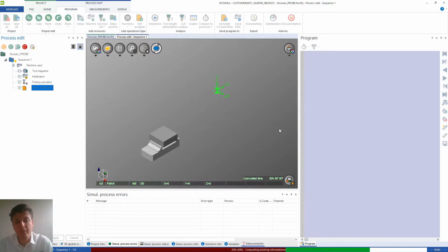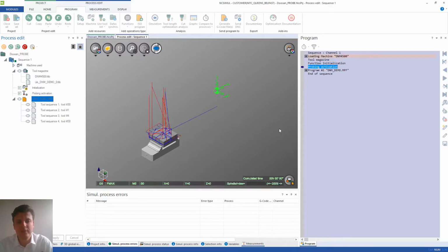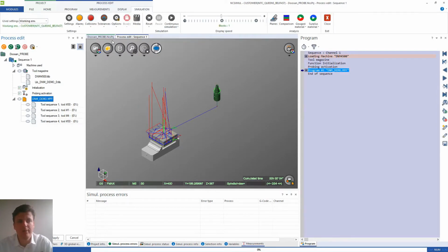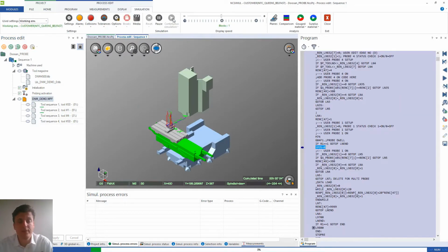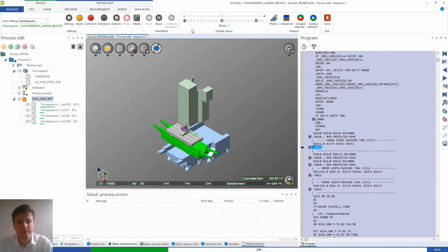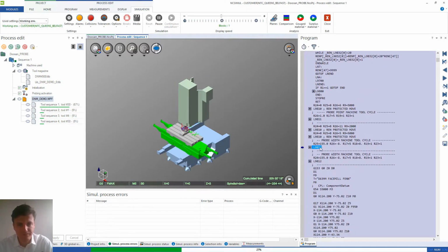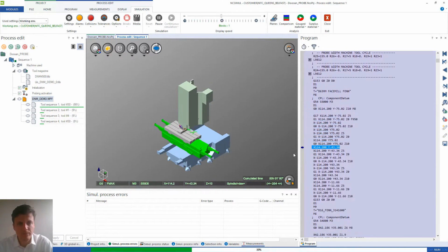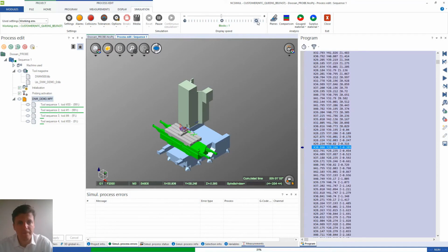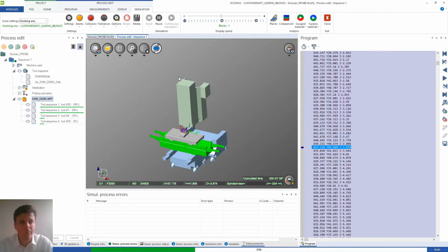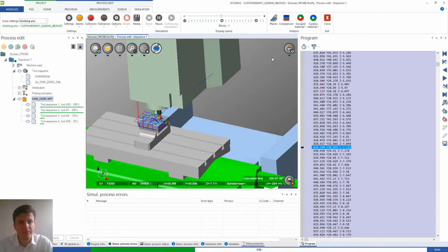The red is, remember, on NCMO, it just shows you it's decoding the probing, and actually it can record the touch probes. So you can output from the virtual environment the printed values. Quick simulation to have the updated stock. You can see this is just a basic 3-axis kinematics running the Renishaw macros, doing the milling. Okay, jump to the end.